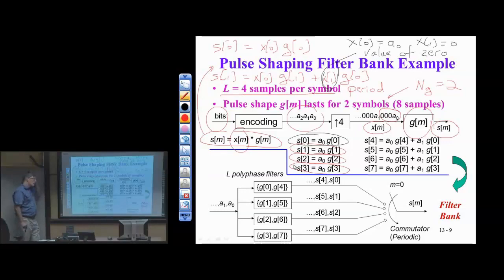Okay, now, once I get to S4, now A1 has entered. The next symbol of samples has entered. So A1 has now entered the input to the FIR filter. And now I have, instead of 5 multiplies and 4 adds, I just have 2 multiplies. I just have to worry about A naught, A1. And so forth. I keep going.